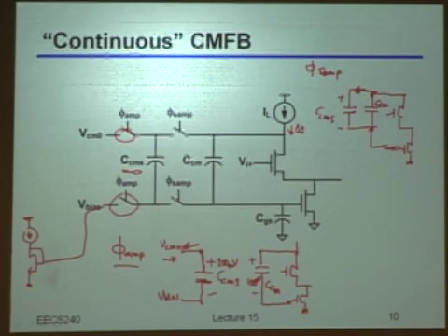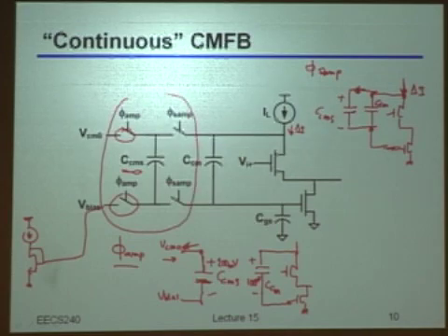So I will have, of course, on both sides, some transfer of charge. Potentially, if I don't have huge disturbances at the common mode, I will soon converge, after some time, to the value I want. On the other side, if I have some disturbances, these are recovered, although not really immediately, but with much less power consumption by the VCM0. Of course, in order to sustain this delta I, I need some constraints on the impedance that the common mode control is seeing there.